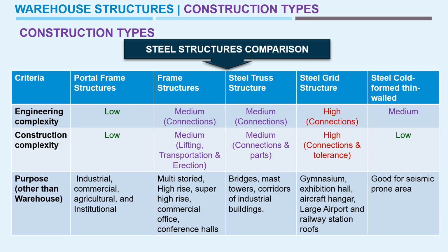And steel grid structure also has high complexity in its connections: where we need to provide hinged connections, where to provide flexible connections, and how many members are to be connected to the same node. These are the challenges while doing the design of steel grid structures.